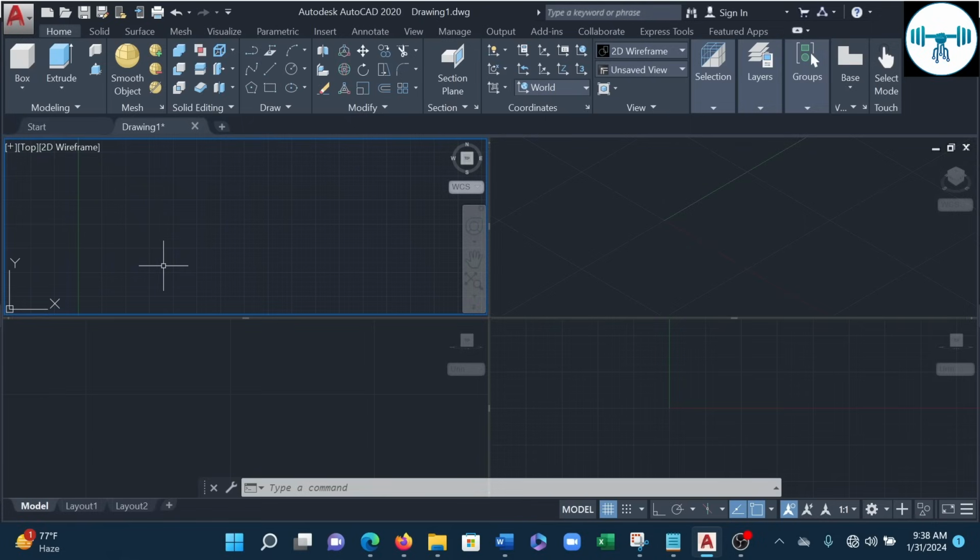What polyline does is that it treats the entire line segments as one. That's the difference between polyline and a normal line. If we draw with polyline, it treats the entire line segment as one, and we can perform the extrude operation. But if we draw with line, the individual line segments are going to be seen as different objects, and that would be very, very difficult for us to extrude. So now we pick our polyline, and then we are going to draw the top of the table.